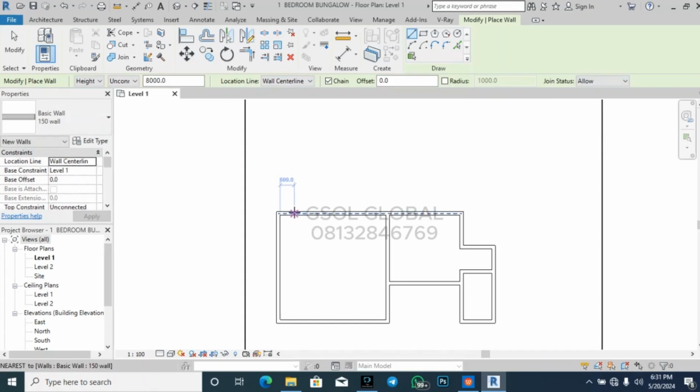Let me create a little recession to make the roof design beautiful. Please note, you don't just draw a straight line wall. That's not professional. You have to envision the roof from the plan. All right, the roof has to be in your head from the plan. But for now, take it bit by bit. Understand the basic aspect properly. Just know how to design a floor plan. Then you can start applying everything.